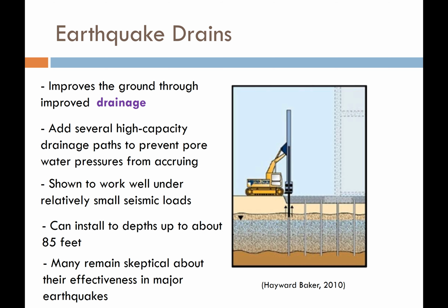A lot of researchers, including Professor Rollins here at BYU, have done a lot of research with these earthquake drains on shake tables, and have shown that even under enormous shaking they do reduce the amount of settlement and the onset of liquefaction. Here's the problem, though. With earthquake drains, your ground is still going to settle.